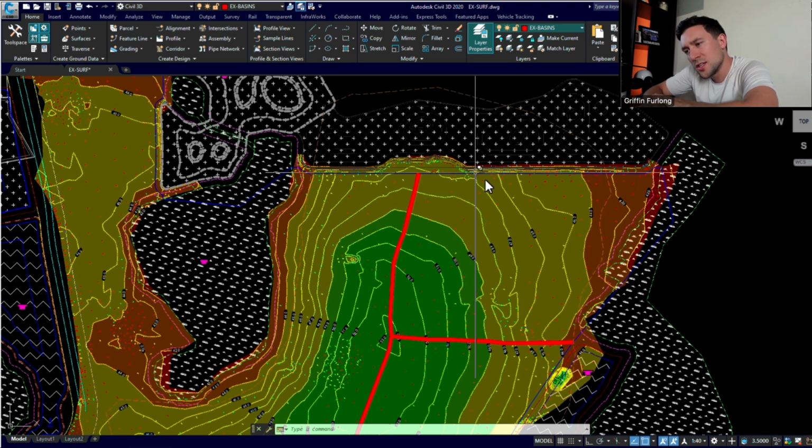But the question is, at what point does this water actually go into the wetland? So what I like to do is just keep drawing these little streams and acting like I'm a water droplet. So if I keep going perpendicular at this point, water kind of wants to break right here and sheet flow into that wetland.